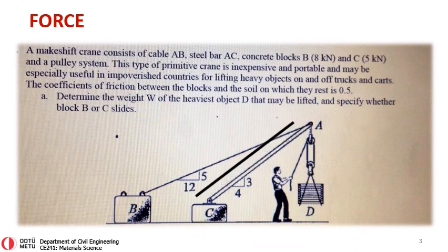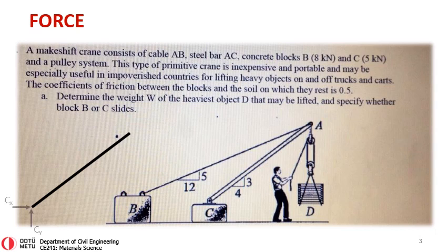Now, let's take this strut and let's look at the forces that are applied on that strut. From this bearing block, the concrete block, there will be some reaction forces, Cx and Cy, and there will be some reaction forces at point A, Ax and Ay.